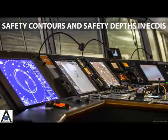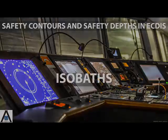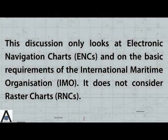This presentation looks at safety contours and safety depths, but focuses on the contours. In some publications, the contours are called isobaths, or lines of equal depths. This discussion only looks at electronic navigation charts, or ENCs, and on the basic requirements of the International Maritime Organization, the IMO. It does not consider raster charts or RNCs.